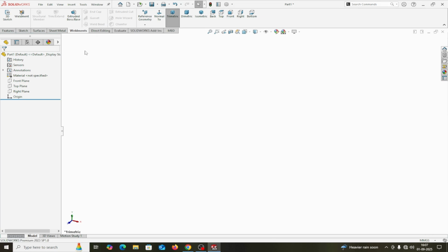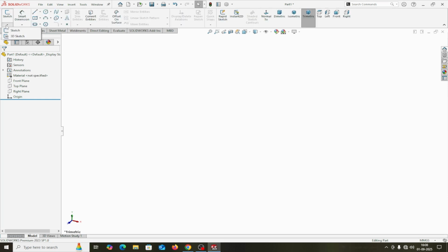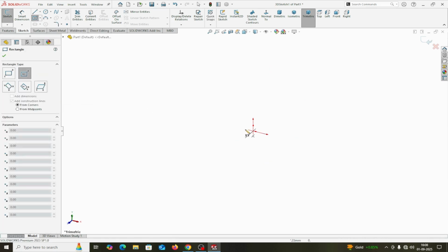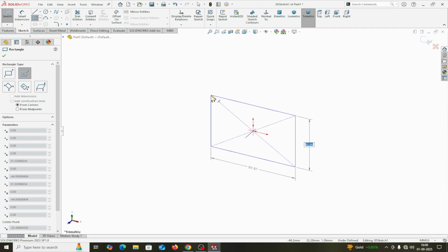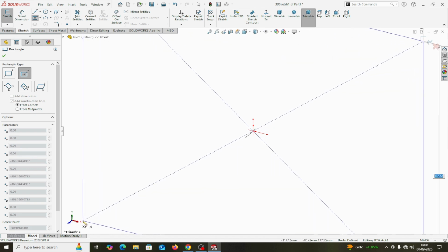For inserting the structural member, first we need a sketch. We will focus only on the structural members in this SolidWorks weldment environment. We take the top plane, we sketch, go into the 3D sketch. Our 3D sketch is going in the XY plane. Near the pencil line, you are seeing the XY icon, but I have to place this X on the Z plane.